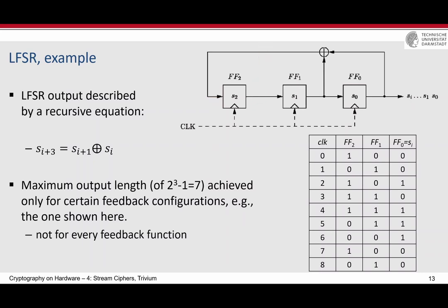And then this is a super small PRNG or LFSR. Suppose that the seed is 1, 0, 0, and the next state 1, 0 is shifted here, and the feedback is 0 because these two are 0, and the output of this will also be 0, then 0 will be saved here. And then you see here, the state is 1, 0, 0, and then we continue till here and say 7. State again is 1, 0, 0.